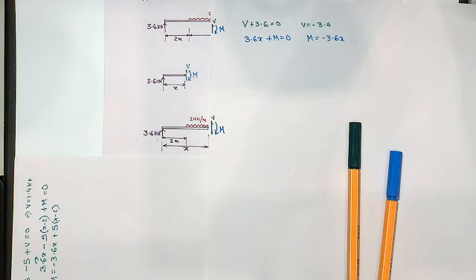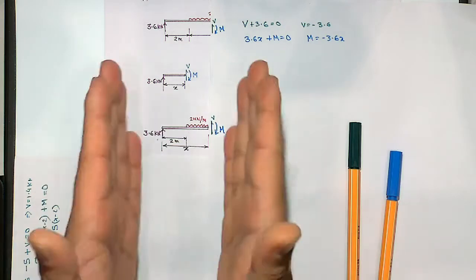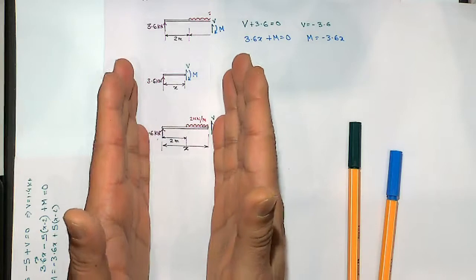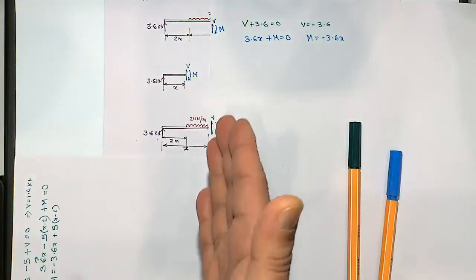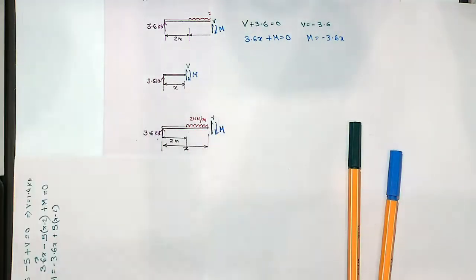So whenever you have a cut, you have to replace that with a force that may exist at that point. It may be 0, but may not be. So we have to assume that there is a force in there. In this case, for a beam, shear force and bending moment. So whenever we make a cut, we have to assume there is a shear force and a bending moment internally acting. We have sort of exposed it to keep it under equilibrium.